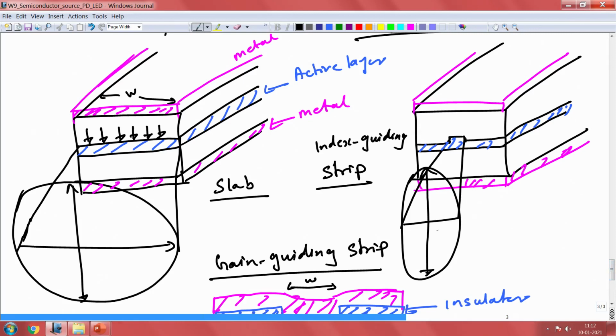There is a parallel angle and then a perpendicular angle, right. In this case this one is parallel to your thin film. So this is theta parallel and this one is theta perpendicular. Okay. These two are the divergence angles that we have, and we should know how these divergence angles could be controlled, particularly when it is index guided.